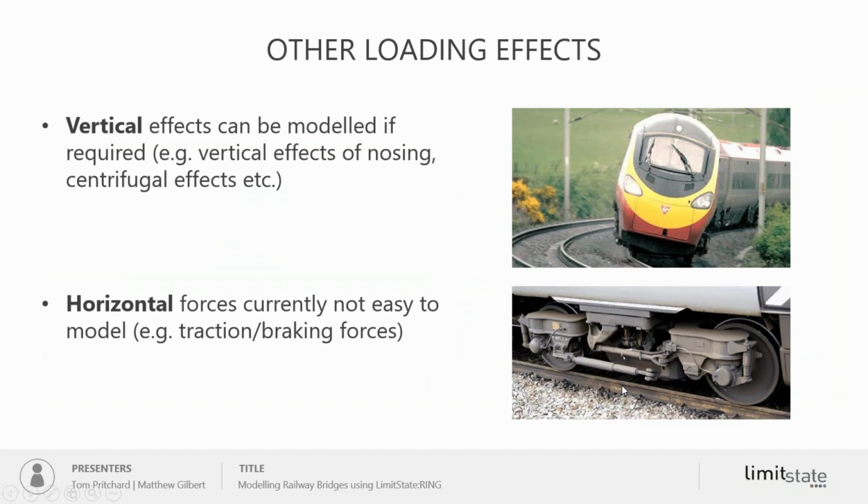Other loading effects, vertical effects, you can model. So for example, the vertical effects of nosing, centrifugal effects. Horizontal forces are currently not easy to model. There hasn't been very much, to my knowledge, in the way of testing of horizontal forces for masonry arch bridges. So at the moment, there remains something of an unknown, and hence there's not a direct way of modelling those in the software.